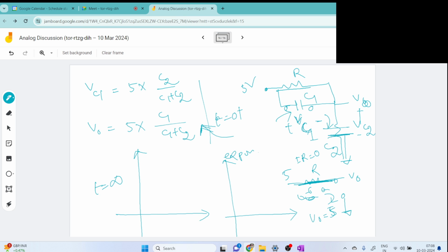This becomes a short circuit, right? So this potential is like this and this potential is like this. Same case. So the VC1 will be zero, there is no voltage drop. This was plus and this was minus, right? And KVL also has to be satisfied.